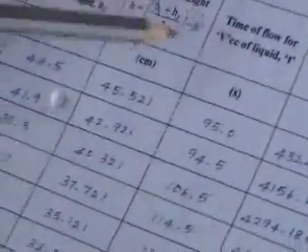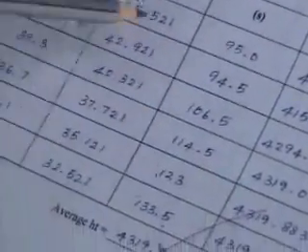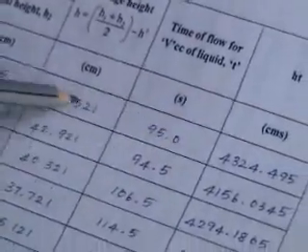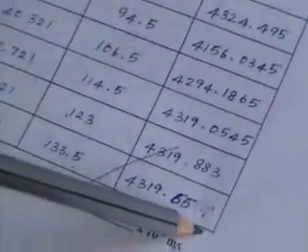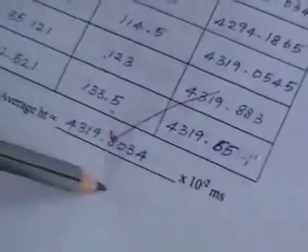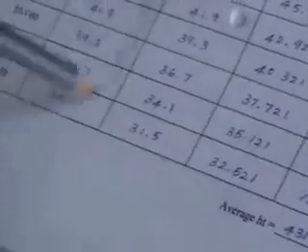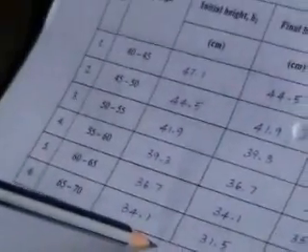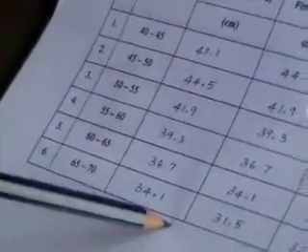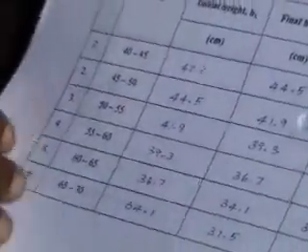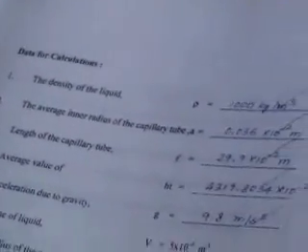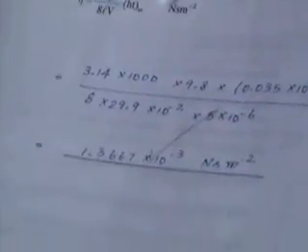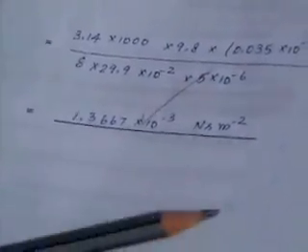So you have the time of flow from the previous tabulation. We have H here, T here; multiply these 2 columns and you get the last column. Take the average of all this and write it down here. Some burettes may not be marked up to 100, you may have only 0 to 50. In that case, you can start your values from 20 cc. As told earlier, do the calculations, note down all the values in the data for calculations, compute the values, and you get the final answer like this. Now this value is slightly high, but it doesn't matter.